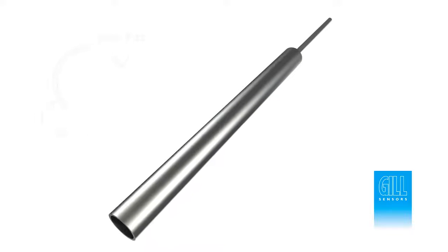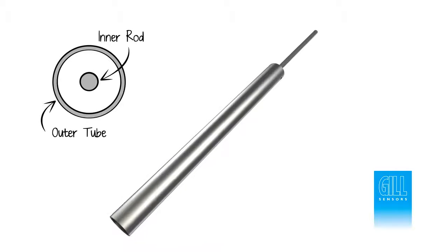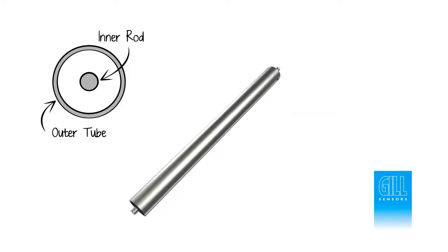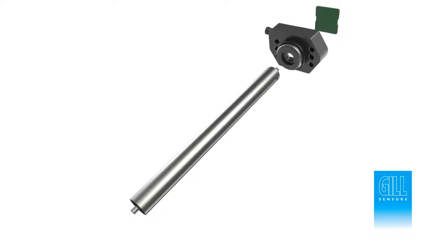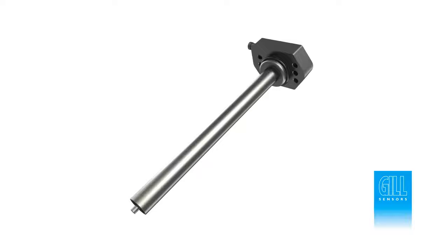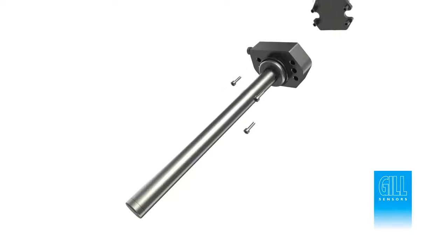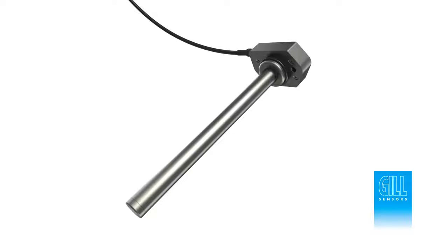Capacitor plates can also be deployed as concentric tubes, with the advantage of reduced interference, as well as improvements in mechanical stiffness and robustness. Fully integrated electronics mean no external electronic units are required, as all signal processing is managed on board. Dielectric fluctuation caused by temperature variation is managed using offset values also stored within the sensor memory. These values are typically applied during factory calibration at Gill sensors.